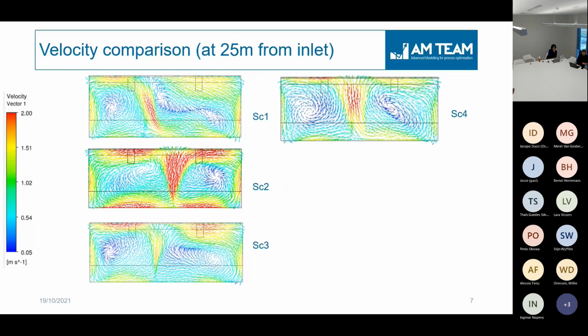And then if you look from the vertical angle, you will also see that they're all at the same location, but you see different flow patterns being formed. These are the plumes which are formed because of the air. So these vertical vectors show the formation of the plume, and in some cases they are different. In some cases they are much stronger, and at a certain location, if you move further, it would change. So they are very turbulent conditions in the bioreactor, which is leading to different mixing patterns.